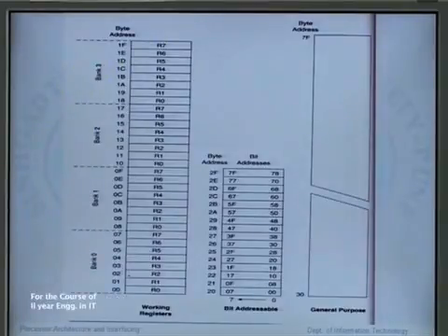for bank 3. Each register can be addressed by name when its bank is selected or by its RAM address. For example, R0 of bank 3 can be addressed by the name R0 if bank 3 is currently selected, or by address 18H whether bank 3 is selected or not.